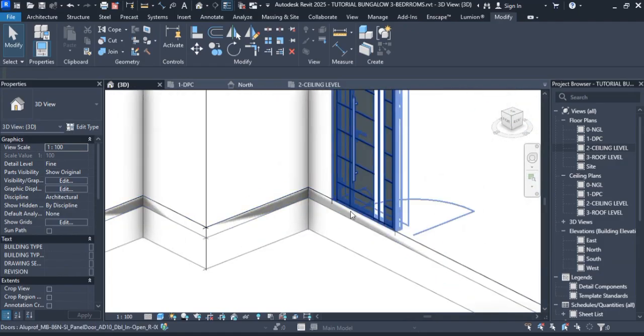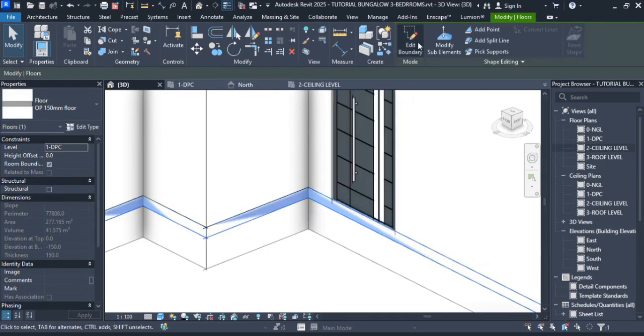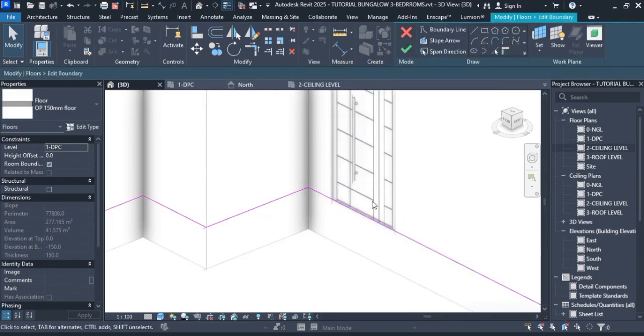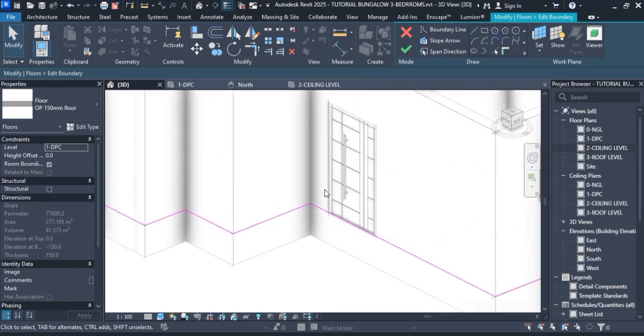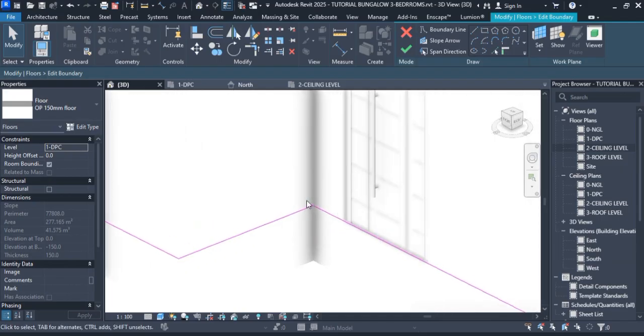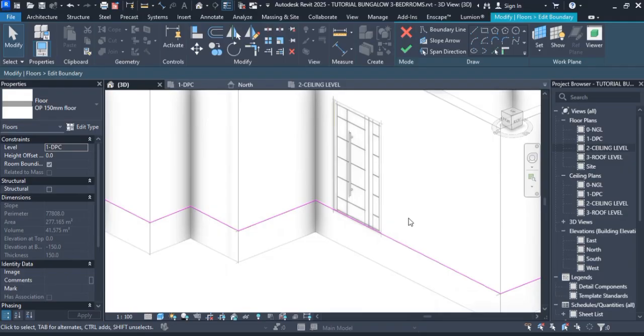I went to the 3D so that I can select this floor easily. Then I'm going to edit type. You can actually edit and draw in your 3D. I know really good Revit users that draw in 3D very well, and the more you draw in 3D, the more you improve in your drawing. Because when you draw with 3 dimensions, you have to obey some rules on alignment. It's going to help you to align better and so many other things.